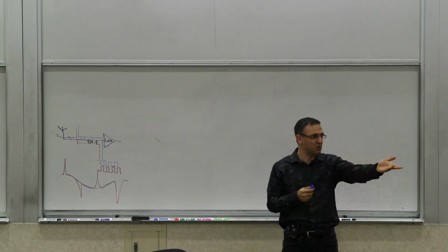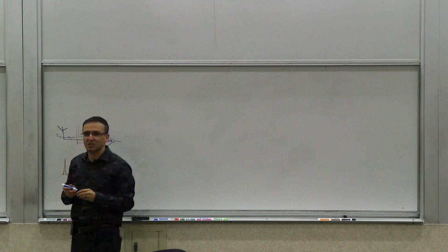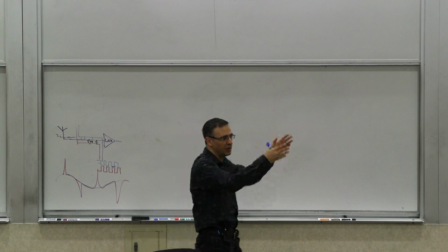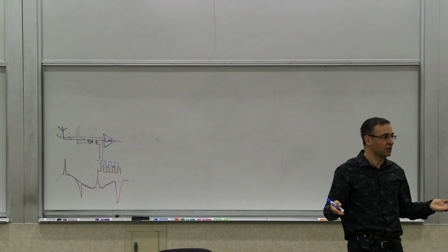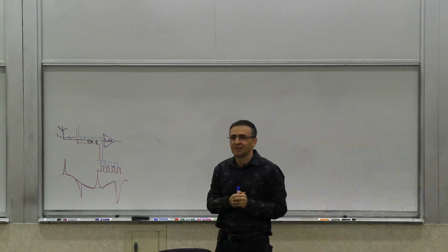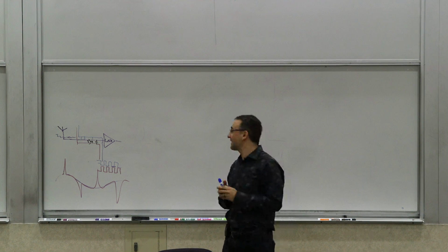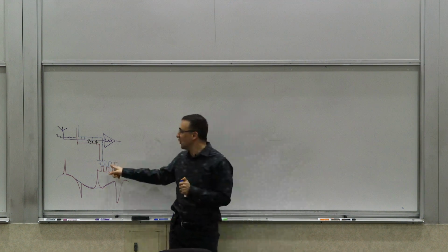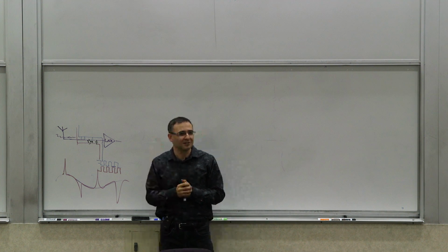Shield it, which is basically reducing the coupling, right? So you put another metal layer here, separate them as much as you can, but how much shielding can you do? Because you have these metal lines parallel to each other on the IC, so you can try to make a tub and put it in there, but you add capacitance doing that. But yes, you can do shielding too. That's right. There was a measure against a copy of the coupling signal, so active cancellation, right? So these are all good ideas. If you know what you're coupling into it, you can try to actively subtract it till it cancels, right?